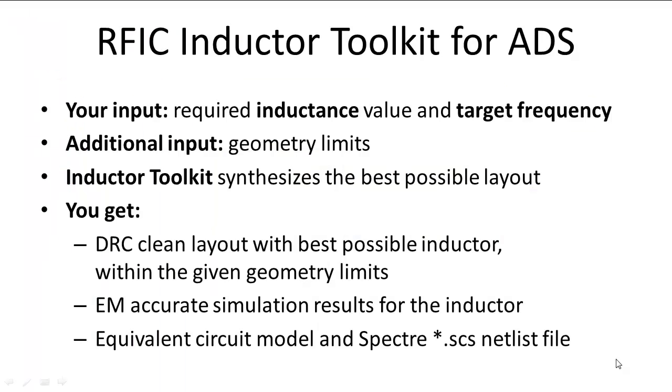Okay, let's summarize what we've seen. We've looked at RFIC Inductor Toolkit for ADS. And we started from your input, your required inductance and the target frequency. You start with the electrical parameters. Also, you had a chance to specify certain geometry limits, which are limited by your technology or just by the available chip space. And then Inductor Toolkit has automatically found the best possible layout within this geometry range.